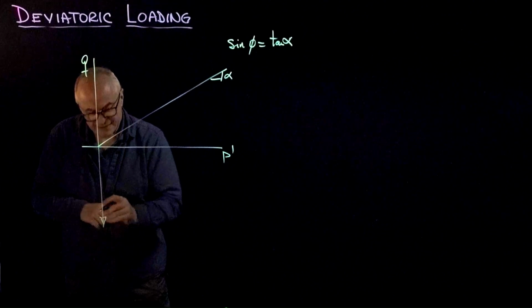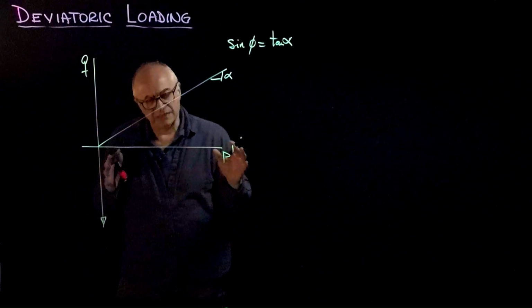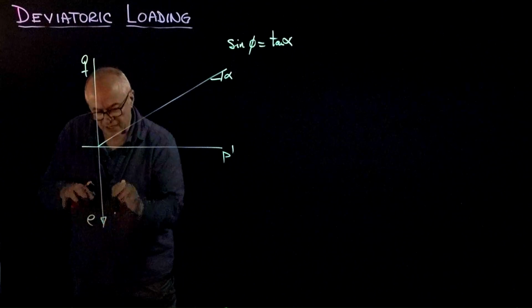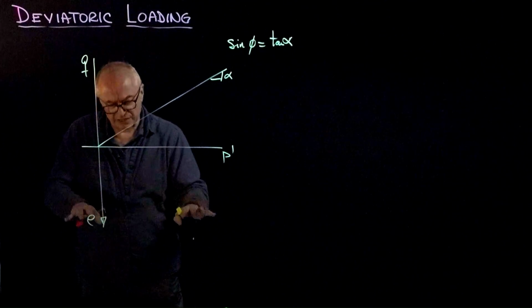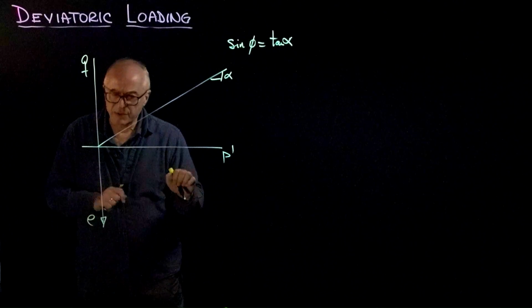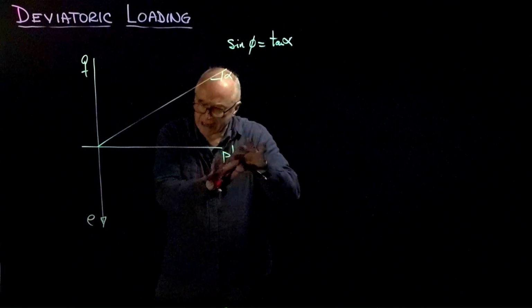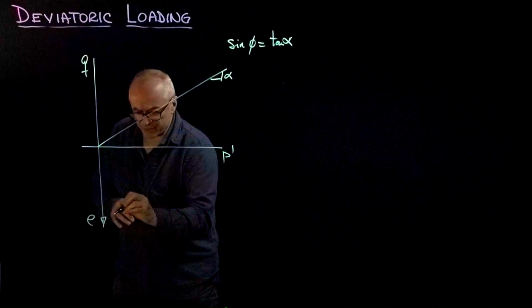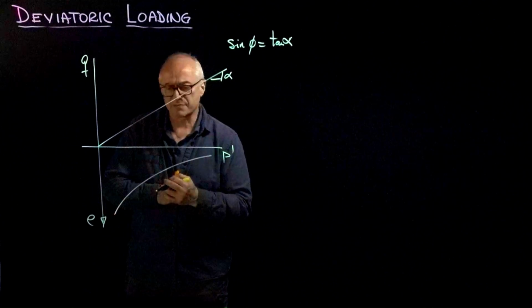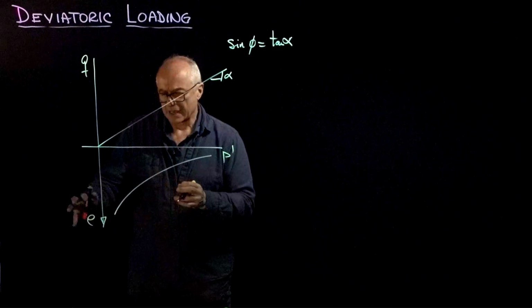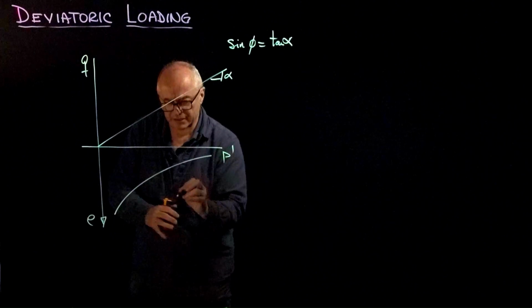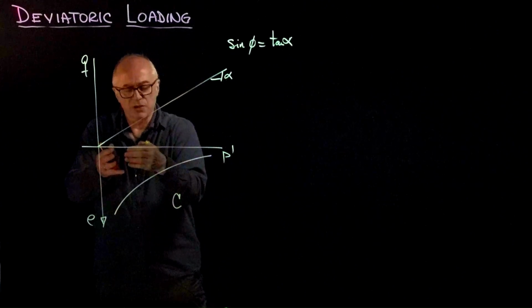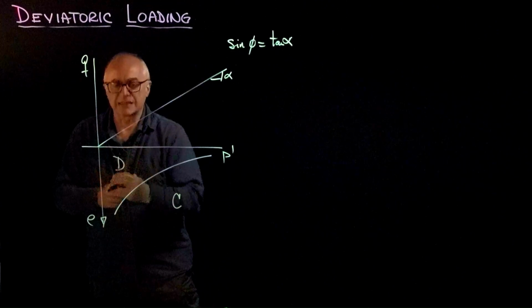Now, summarizing the previous discussion related to the elevator, we realized that if soils have a large void ratio, they will tend to contract. But they will also tend to contract if they have a high confining pressure. Therefore, we can pretty much split this space in 2 regions. High void ratio, high confinement, this is contractive. Low void ratio, low confinement, this will be the dilative regime.